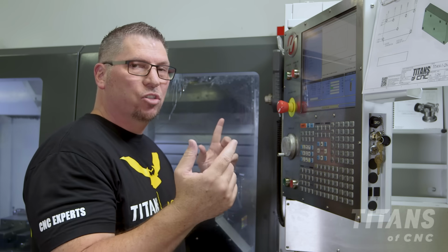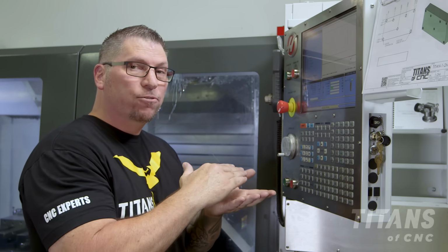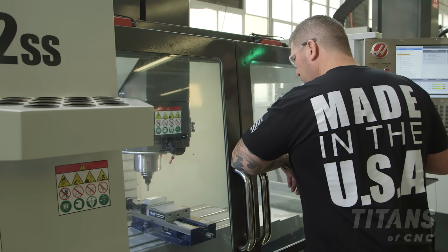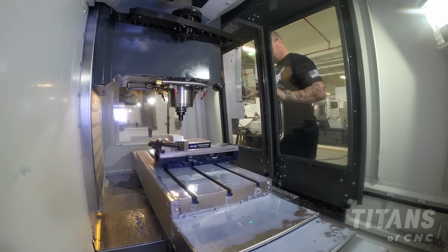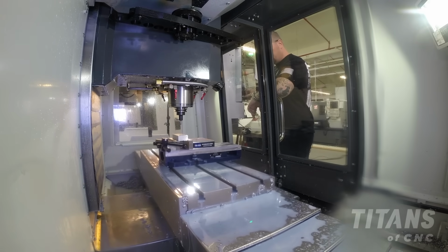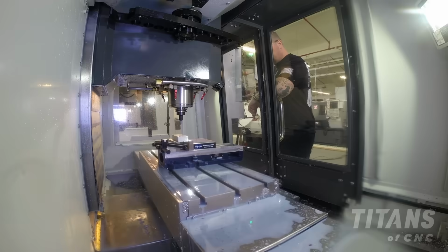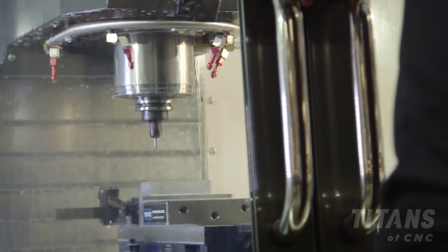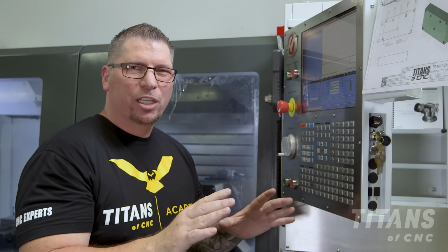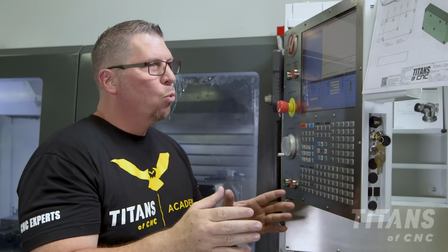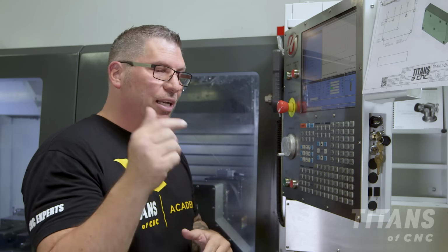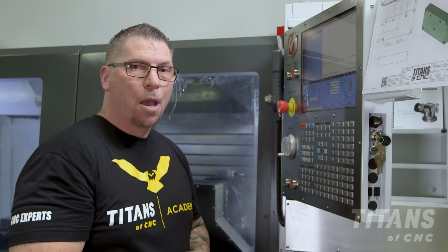So now I just have to take my tools, offset them about 6 inches off the part, and then I'm going to dry run the entire program to make sure that all the tools function perfectly. I'm going to drop my feed rates, my rapid, and double check everything to just proof it all out. Once I've had success, we can engage the material, we can make a part, boom!